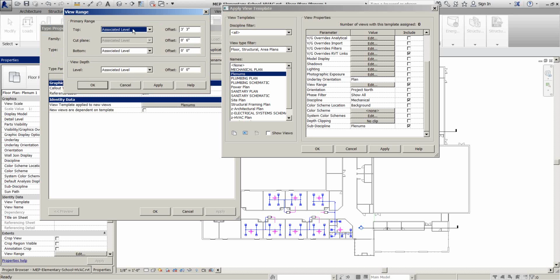If you've been struggling with trying to cut back on the time that's spent making a project in Revit, the more you do up front, and I mean before you even get the project, before you even get the contract, there's things you can do in Revit that will make the project go a lot faster. Most of them are in your Revit template. So if I have view templates set up ahead of time, when I get the project, I create a view, bam, my view is set up.